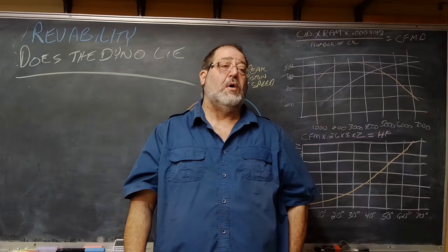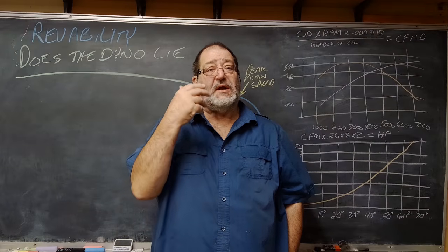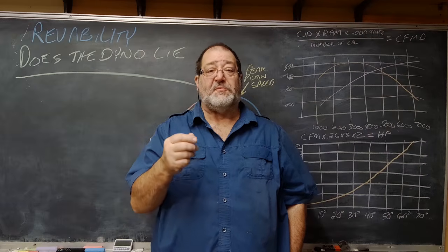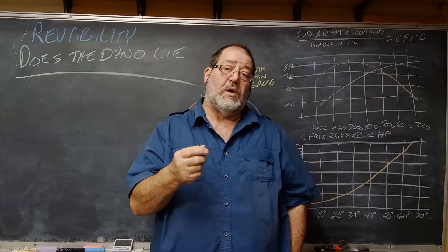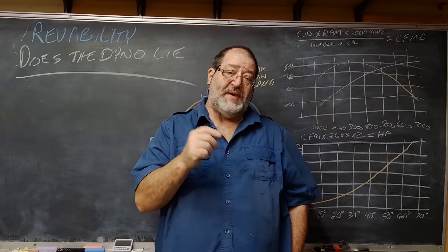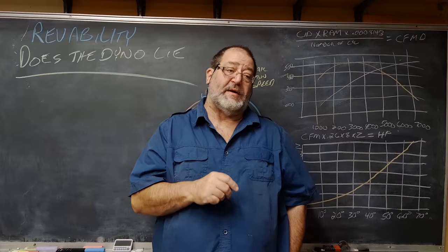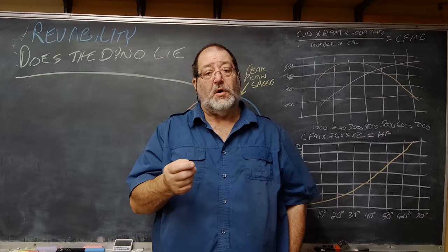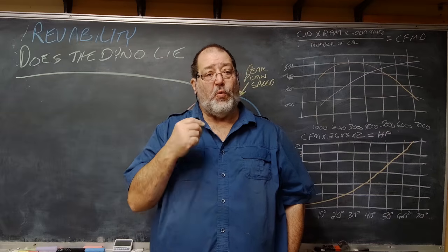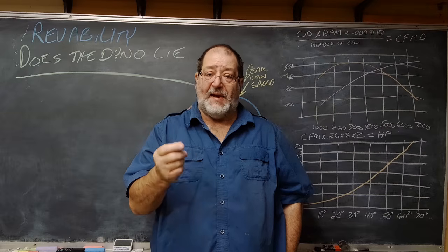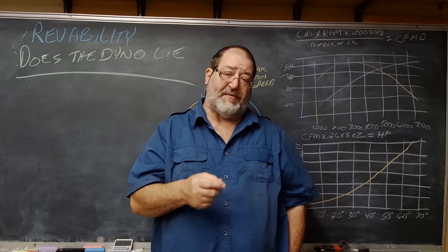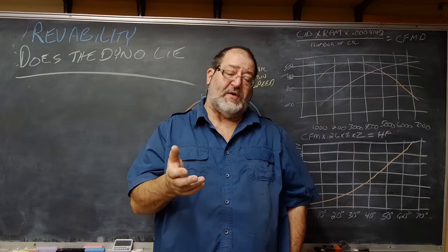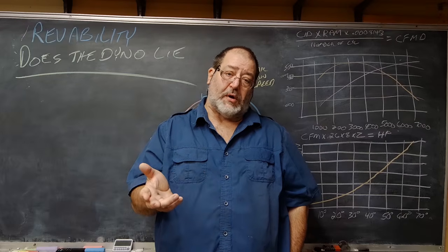And so you can listen to how it does on that load-in. You can sometimes go to a lower RPM and load in to see how it does, because that load-in will tell you how well the engine may behave out on the street and driving. But the rate, like I said, is controlled by the computer.